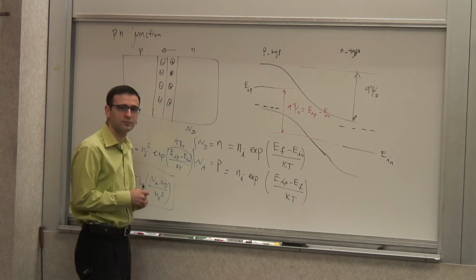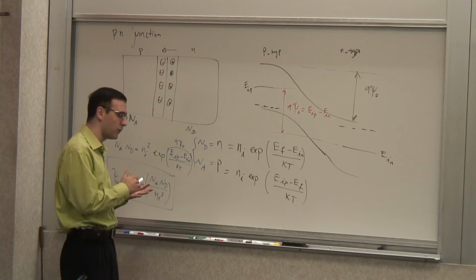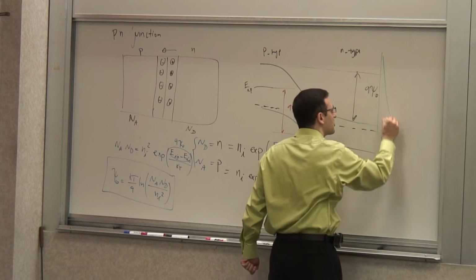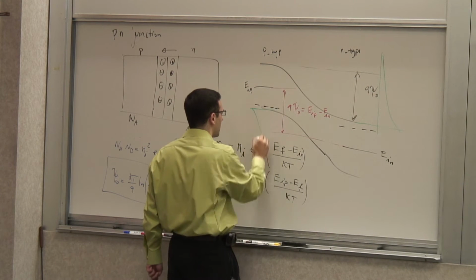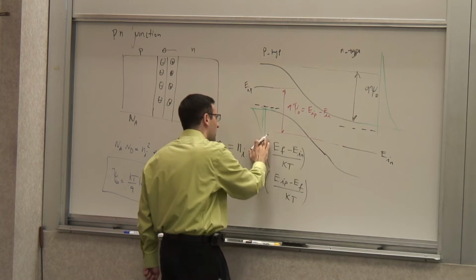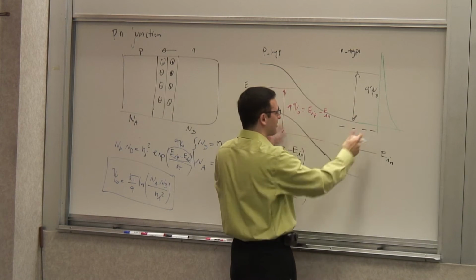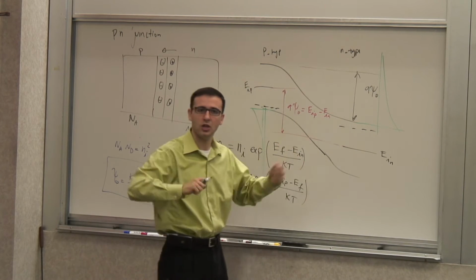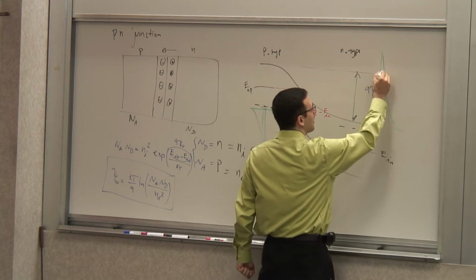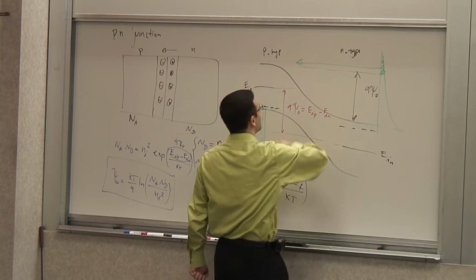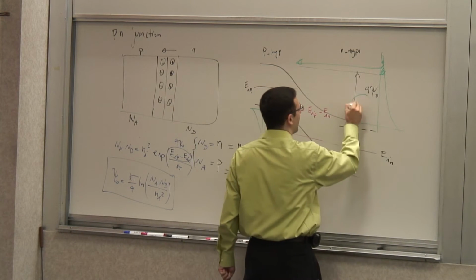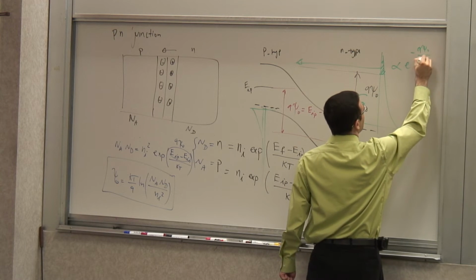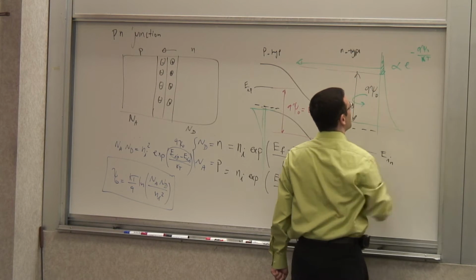And then we applied forward bias. When we applied reverse and forward bias, and we saw, well, even in the case where there is no bias, there was a distribution of electrons here and distribution of holes, which we approximated using the Boltzmann distribution. So there are some of them, they're moving randomly, right? Thermal energy. The electrons on this side and the holes on this side have thermal energy. They're moving randomly. And every so often, one of them has enough energy and is moving in this direction so that it can cross. And the remaining ones are bounced back. So the number that can cross is proportional to e to the minus Q psi naught over kT, according to the Boltzmann distribution.